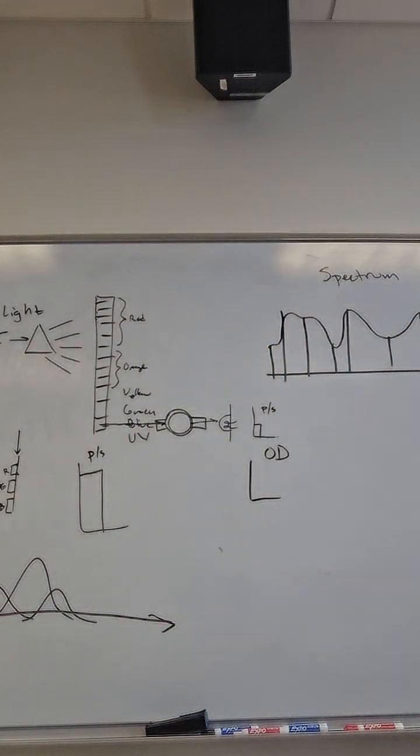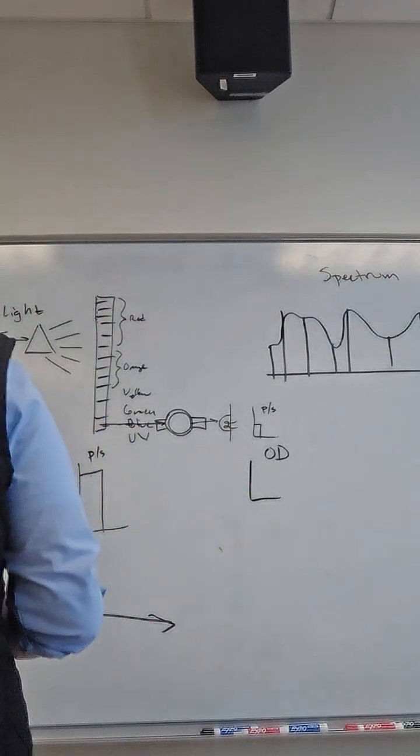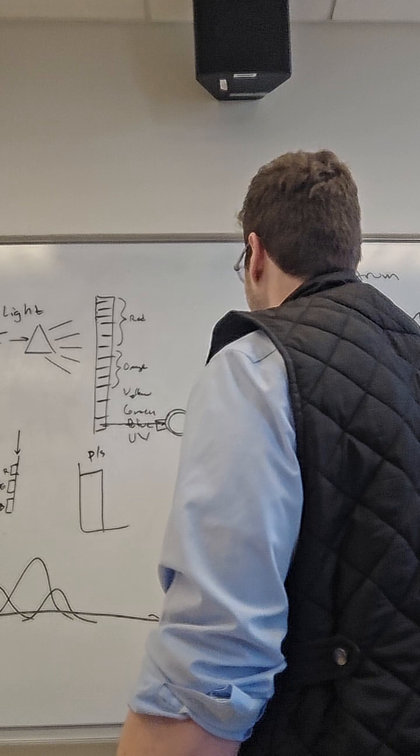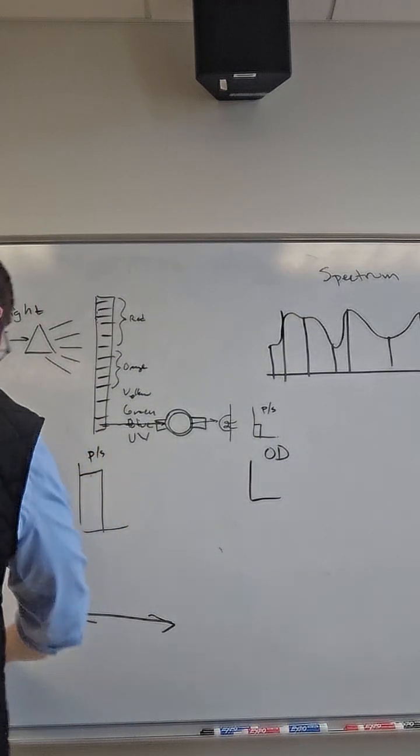And that is just, in a nutshell, how colorimetry works in industry. Like I said, lots of things, literally sometimes producing paint. You want to have a very specific color of paint in your industrial process. And your PLC might be tweaking the amount of ink that goes into that paint, or the amount of white versus the amount of gray. I don't know if you're trying to dial it in. So some part of your process may very well be an outcome, a spectrum, an intensity that you'll have to keep an eye on while you're monitoring your process.